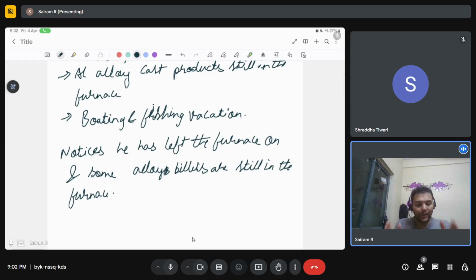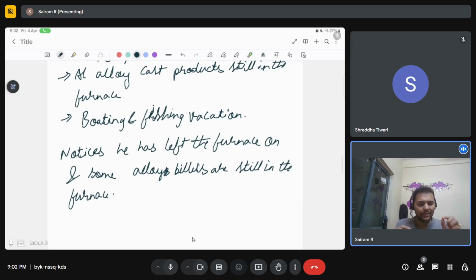So he understands that with time he has been able to strengthen the alloy, and then he cuts the sample and goes back to see the sample microstructure under SEM, under TEM, under microscopy. He is able to see fine precipitates being formed in the aluminum alloy matrix. He determines the composition of those precipitates, and then he does a time temperature dependent study on these materials to understand the mechanism of these heat treatments.